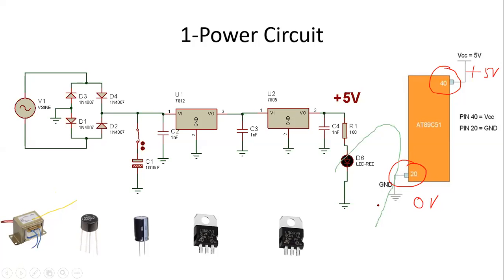Well, you can connect directly the plus 5 volt and ground from the regulated power supply in the lab for learning something. But when you are designing a product where this microcontroller is going to be part of it, obviously you need to design an independent power circuit which supplies the necessary power for this particular microcontroller. You cannot obviously ship that particular product along with a regulated power supply. So it is always necessary that you design a small power circuit which not only powers the microcontroller but also powers the other accessory circuits.